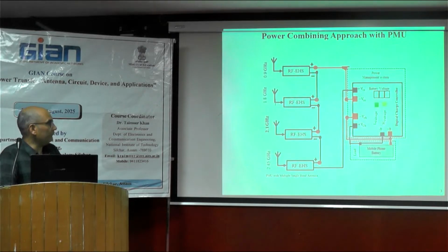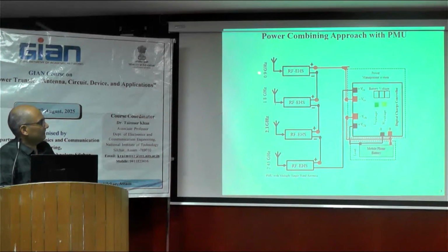Moving ahead, the same scenario means power combiner with power management unit. It is a standard unit available with different names in the market that we can use directly or we can design ourselves also. That is equivalent to a voltage regulator kind of thing, because these source energies will be varying in the atmosphere. Finally, after taking each one, the combiner output is fed to the PMU, and finally at this point you will get the regulated or stabilized output from the PMU.